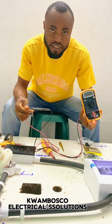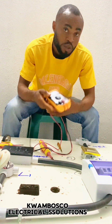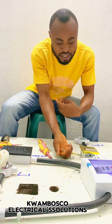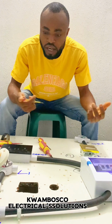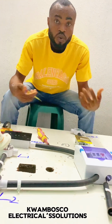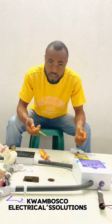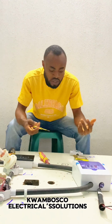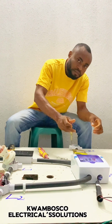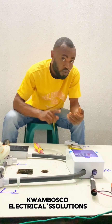I don't know if you can hear the sound. So this is the sound of continuity. So in the absence of this, let's assume you don't have this and you had already done your connection, and after running everything, your client calls you a few days after and tells you that, okay, what you did, the socket is shocking. If I touch it, it's shocking me. So how do you solve this issue? As I had earlier explained, sometimes when you screw it, the screw comes in contact with the live wire. This is one of the things that causes it.